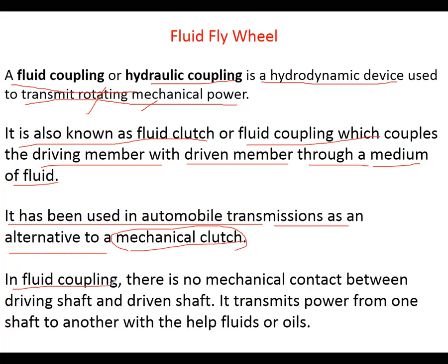In a fluid coupling, there is no mechanical contact between the drive shaft and driven shaft. As we know, in a mechanical clutch, there are plates, and between the plates there are friction pads. The pads and plates are pressed into contact by springs through the pedal operation, so that power is transmitted by engaging and disengaging.